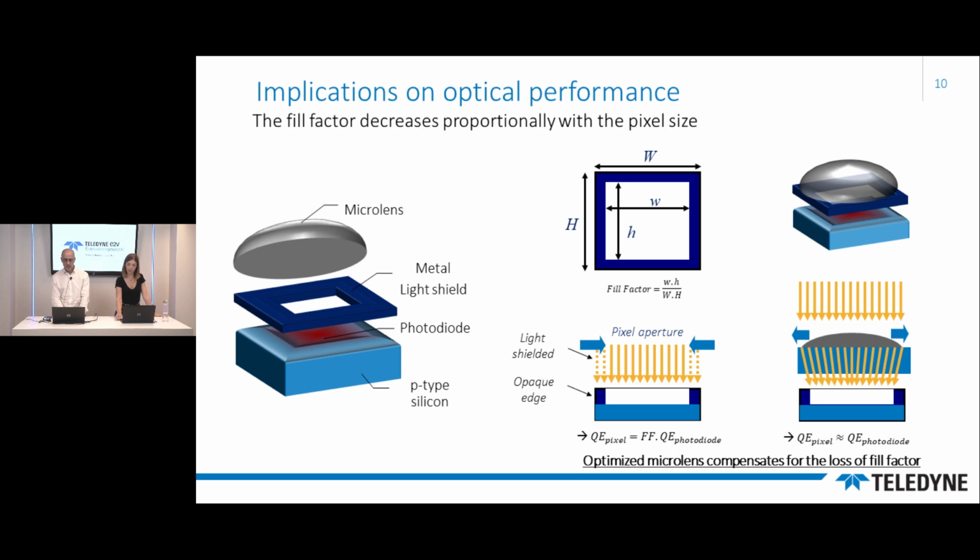A difficulty arises when the light rays from the border parts of the pixel are focused on opaque parts of the pixel, such as metals. This may lead to a loss of optical efficiency, of course, and the microlens shape must be optimized for each application with a real optical design that works at the semiconductor frontier.